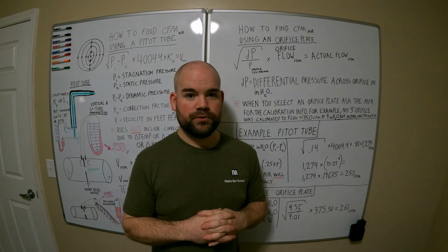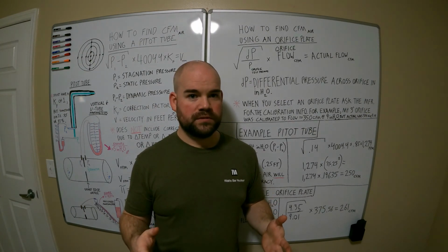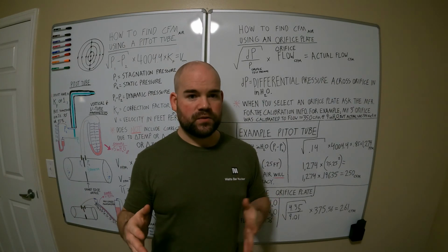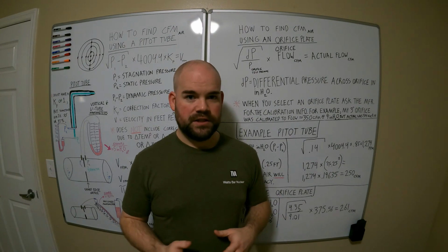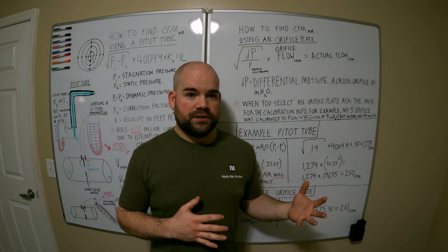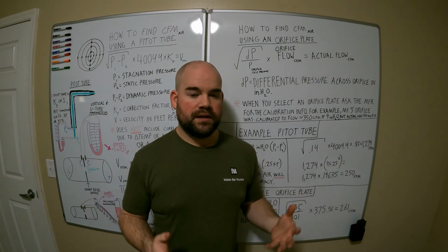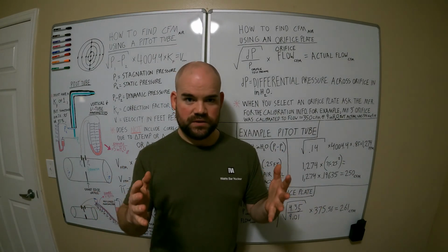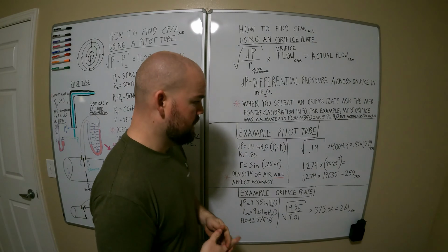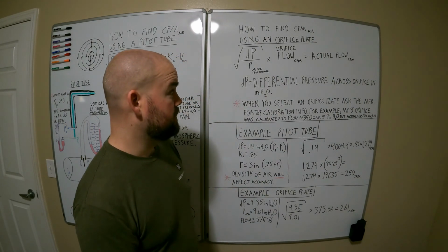Unless they have an intercooler, water methanol, or E85, and you're just on normal 93 octane gas, that's why you're boost limited and knock limited, because pre-ignition is going to happen a lot easier since your temperature rise is so high. So that's what that means. That's why it's important. So keep flow testing, keep working on it.